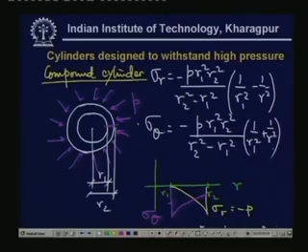Now, that is very effective, because now we have initial stress which is compressive. Now, we apply internal pressure, then a tensile stress will develop, and even if this tensile stress is quite high, the resultant stress will not be that high because of this compressive stress. Now, let us look at what happens to the outer cylinder. This is so far as the inner cylinder is concerned.